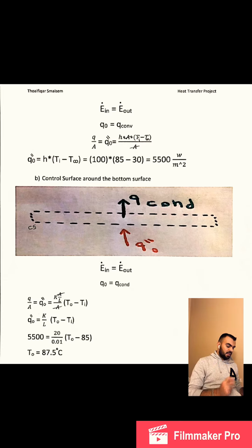We are given the thickness, which equals delta T, again, hot minus cold. But in this case, the hot temperature is the T s, because it is closer to the heater. So it's absolutely going to be hotter. Minus T inner, which we already know, and it's 85.